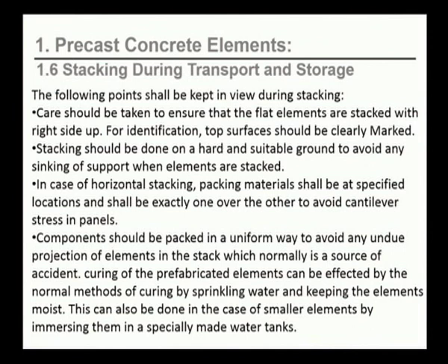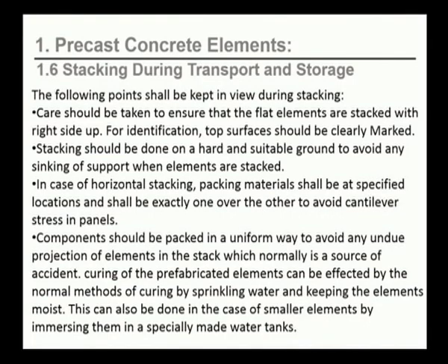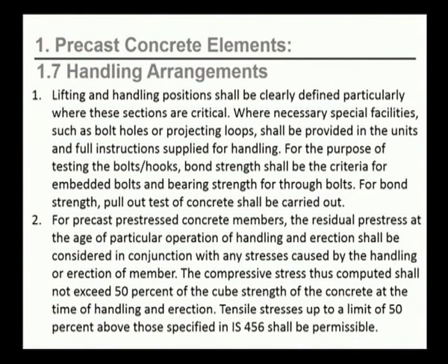stacked together. In case of horizontal stacking, the packing materials shall be at specified locations and shall be exactly one over the other to avoid cantilever stress in panels. The components should be packed in a uniform way to avoid any undue projection of elements in the stack, which normally is a source of accident. Curing of the prefabricated elements can be effected by normal methods of curing by sprinkled water and by keeping the elements moist. Next are handling arrangements.